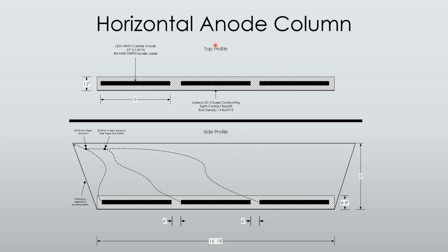So if we use the word vertical, that implies that horizontal exists, and it definitely does. If you have access to the soil, you can create a trench, you can dig down, and you can layer anodes exactly like this in a vertical fashion, just in a horizontal manner. And this effectively becomes one giant anode. So you want to put anodes in periodically enough so that you have good current distribution and that your coke bed is active. But yeah, surrounded by coke, you get effectively one giant anode. Works pretty well for current distribution in the right situation.